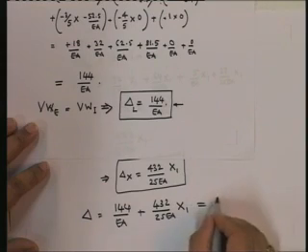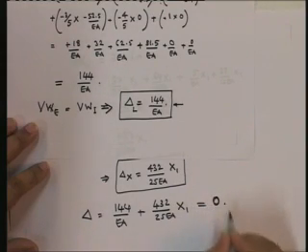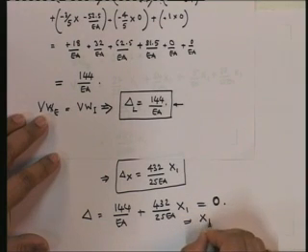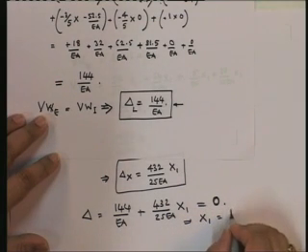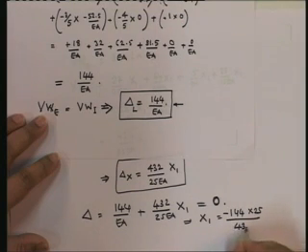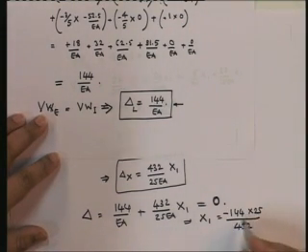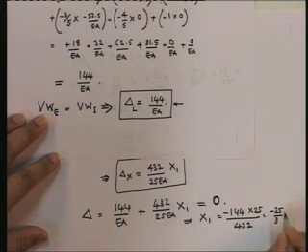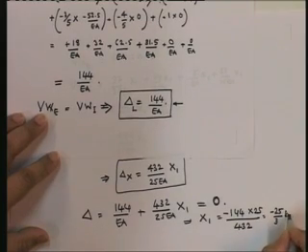And what's the actual delta? In the real thing, delta is equal to 0. From this you can find out x1 is equal to 144 minus 144 into 25 upon 432. So this is going to be equal to minus 25 upon 3 kilonewtons.